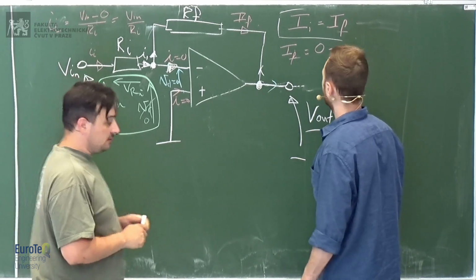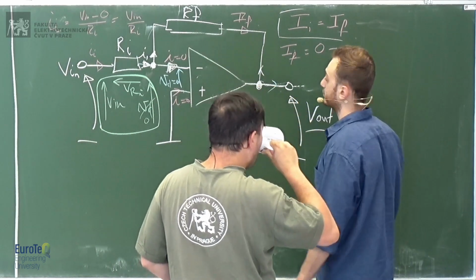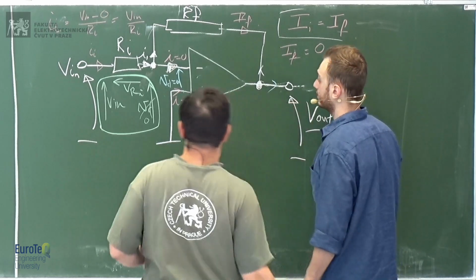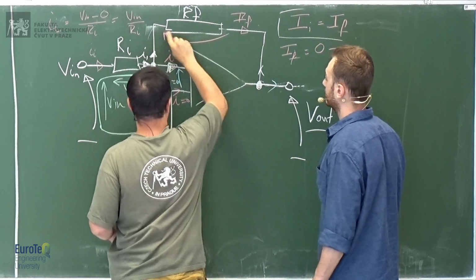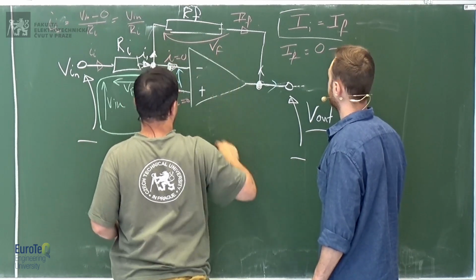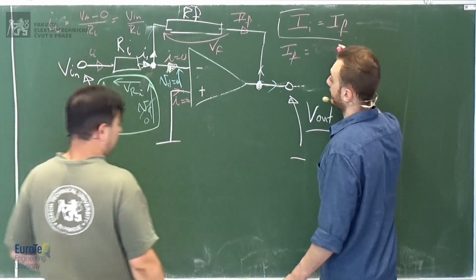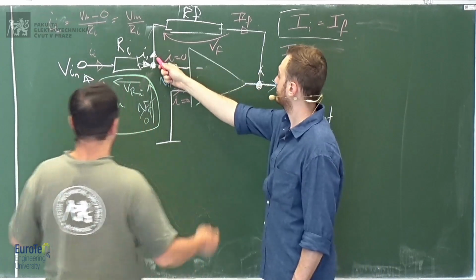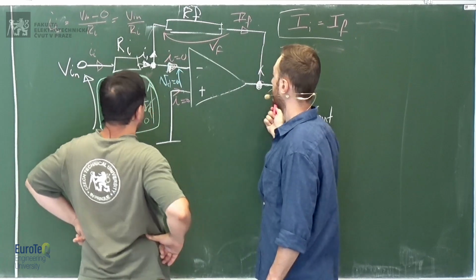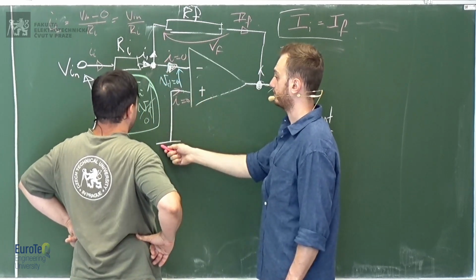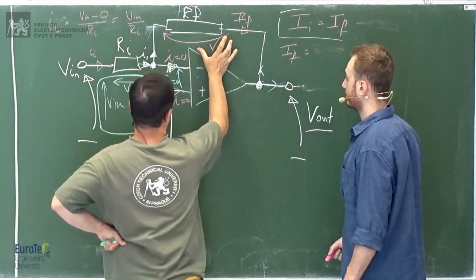What do you mean by describe? Well, we need to express it with respect to the voltage, voltage over resistance. Can I describe this voltage? Let's call it VF, as a function of IF. Well, the voltage here is going to be VA minus V out, but the voltage here is 0 with respect to ground. Let's get to that point later. First, tell me how large is the VF.